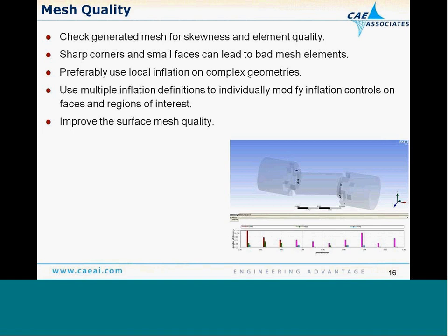In certain cases where you're having a complex geometry, where you run into problems like this, I would prefer to use local inflation over automatic inflation because it allows me to use multiple inflation layer definitions in order to modify these faces, and I can focus only on those regions of interest where I want to modify the mesh. If you improve your surface mesh quality, it will definitely help you with improving the overall quality of your mesh.